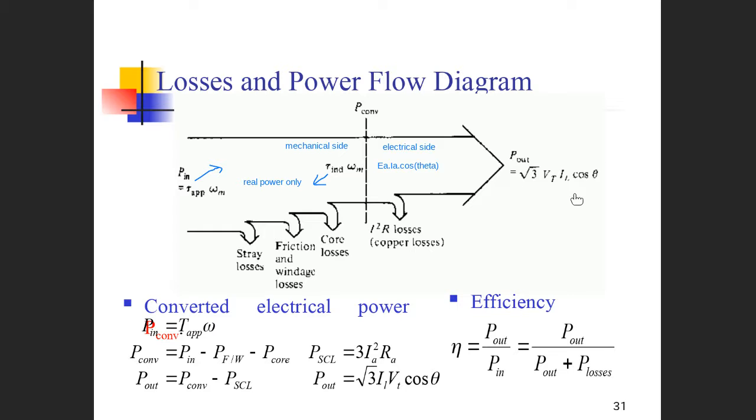Theoretically, if the electric power output is 0, that means the loading current is 0. If the loading current is 0, then you have generated voltage here, but you have no energy output. And the air gap induced mechanical energy is also 0. The torque will be 0. You have the rotation here, but you have no torque, so no force there. So the input energy is just the losses to overcome the friction, windage and the core losses.